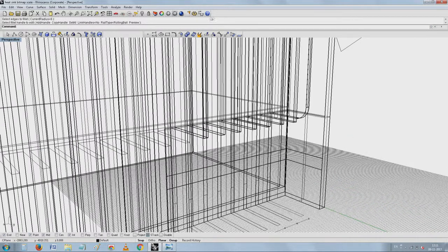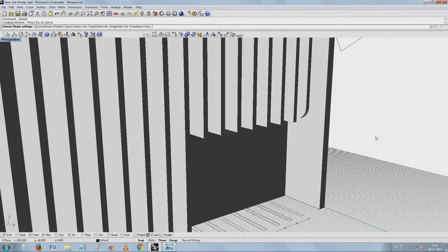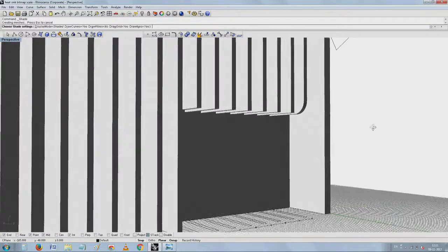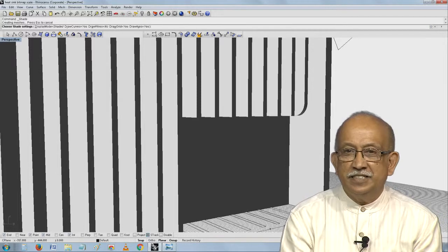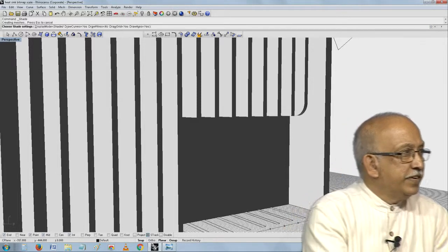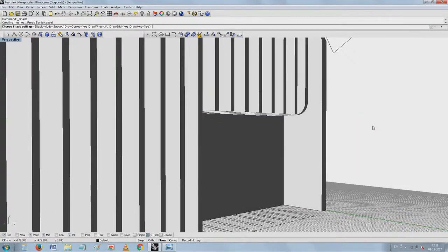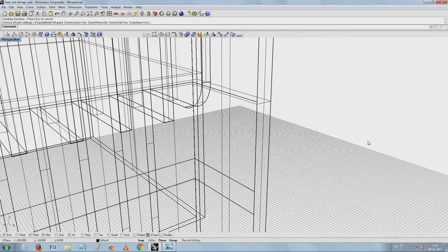See there, it has become rounded, because what I expect is when you are trying to operate a control, most likely we would like to have a smooth rounded edge and not a chamfered edge. So, now I can continue this filleting with all the surfaces that are present here,